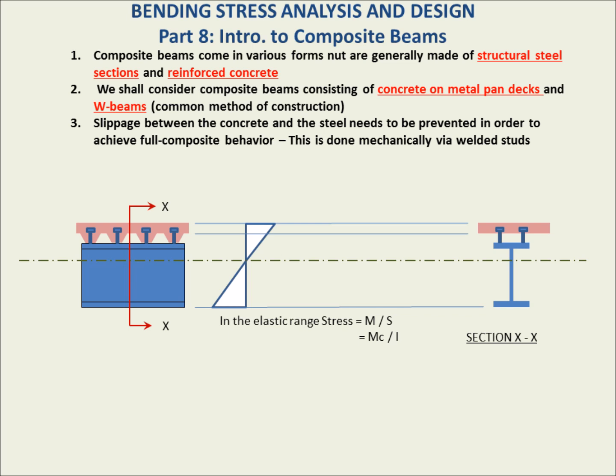However, we're dealing with two different materials that have two different stress-strain relationships, two different numbers, the elastic modulus, that represents their behavior in terms of stress and strain. Their stiffnesses. It turns out that steel is a lot stiffer than concrete. So for a given strain value, steel will be experiencing a whole lot more stress because it takes a whole lot more stress to strain steel that equal amount that you're straining the concrete. The concrete will have less stress than the steel.